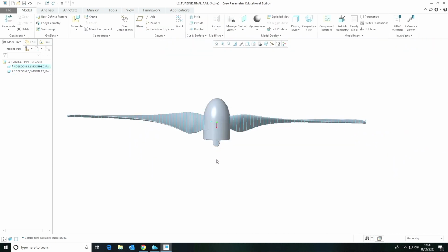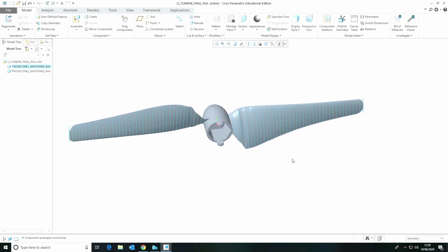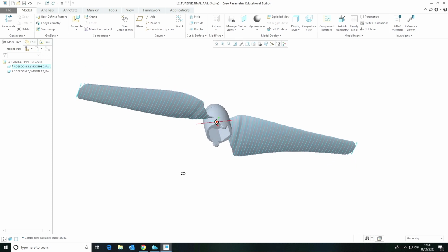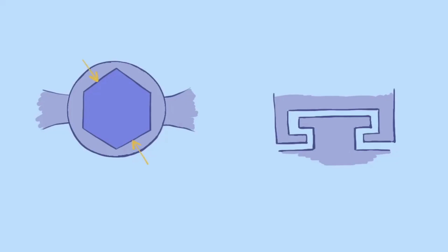The folding nose cone was fully integrated with the blades as shown. The inner aerofoil section was already cleared to withstand the loads through earlier structural analysis in MATLAB, and this method of integrating the blade ensured as much of the turbine as possible was contributing to the aerodynamic performance. Clearances of at least 0.3mm, the printer resolution, were allowed for everywhere, including in the hole in the nose cone for the hub to fit into during testing.